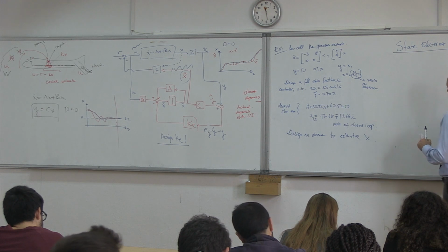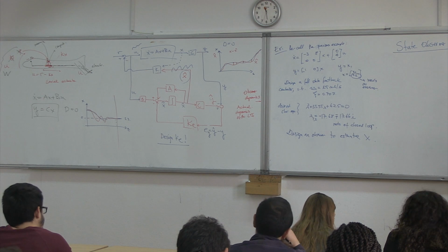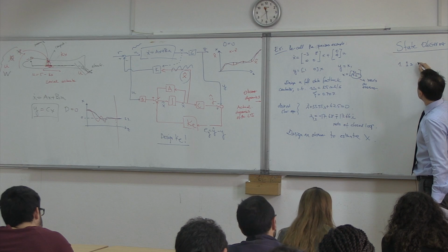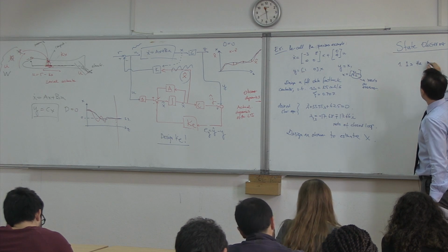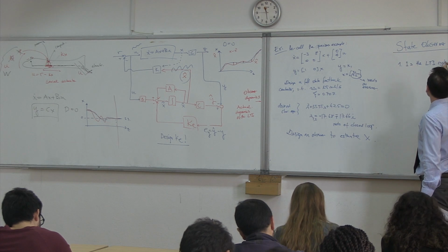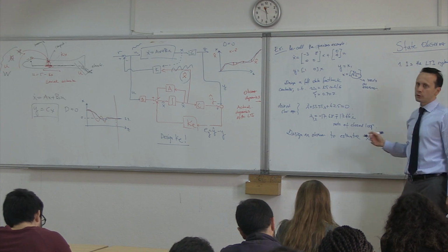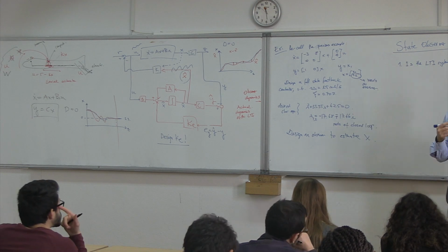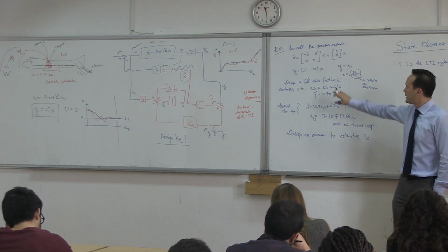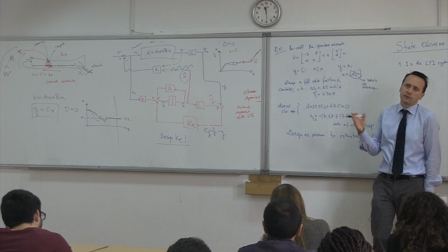So the first question is, of course, what do we do? If you design an observer, what should we look at first? Is the LTI system, linear time invariant system, observable? Because if it's not observable, none of these things will apply. It means some of the x's we can't see by looking at y. So looking at y and u, we can't estimate x.